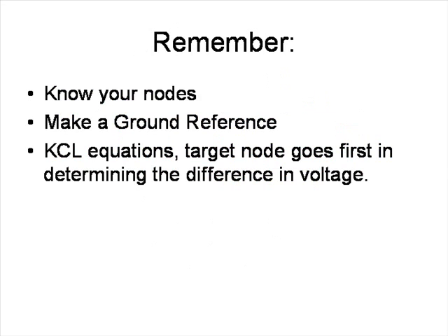So remember, know your nodes. So know where all the nodes are, make a ground reference, and write KCL equations. Target node goes first in determining the difference in voltage.